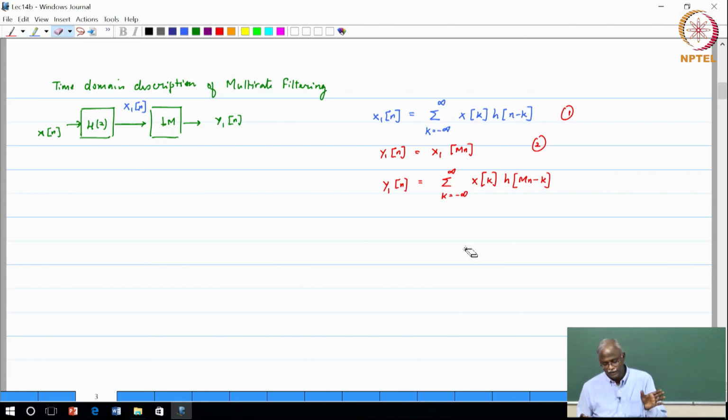So, in other words, you do not take the entire impulse response, you take some shifts of the impulse response, not all of them. When you think of it in terms of the convolution, I do not need all the shifts, but at any given shift you will take all the inputs for doing the computation. So, you can find interesting ways of interpreting this result. I will leave that as an exercise, or something that you can write down as an additional note to this one.